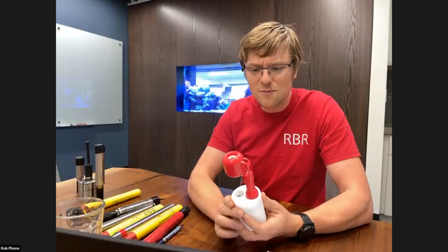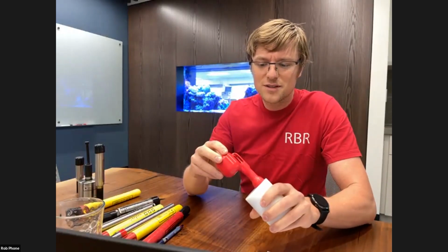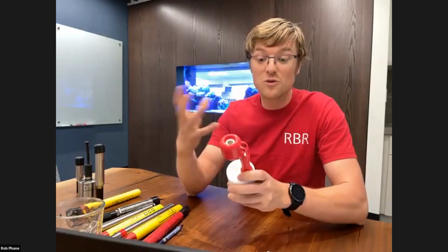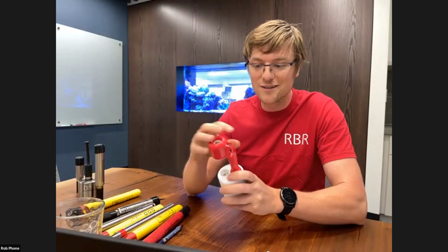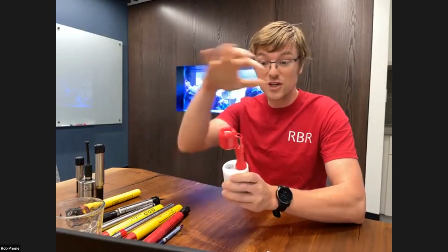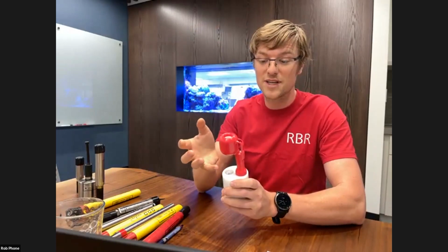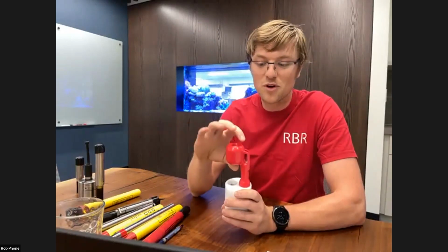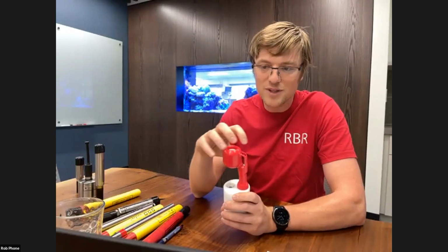It's also a pretty robust design. It's mostly susceptible to macro fouling. Any micro fouling, like small films, doesn't really affect the measurement because it's measuring quite a large volume of water around the cell. This sphere of measurement can extend up to 15 centimeters away, with the bulk of it, around 80%, happening within the cell and the remaining 15% in the volume around it.